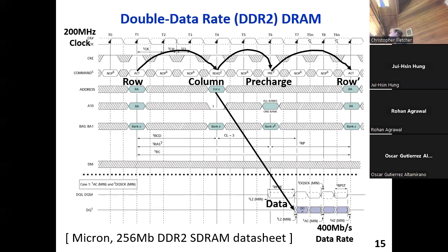This was a big decision on their part, so they must have had a good reason to do it. You take the counterfactual and instead live in a world where the bank address bits are not explicitly split out of the address. So all you're presented with as the user is an opaque address bus and you have no idea which bits are responsible for the RAS versus the CAS versus the bank.